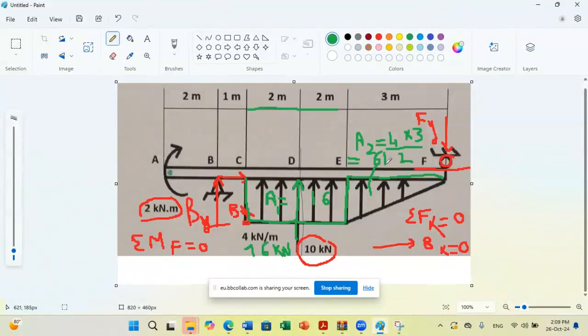And concerning the location, for a triangle, we know that the centroid is at 1/3 of the height from the base and at 2/3 from the extreme point here. So if this length is 3 meters, the centroid is at 2/3 of this length from the extreme point. So this distance is 2/3 times 3 equals 2 meters.